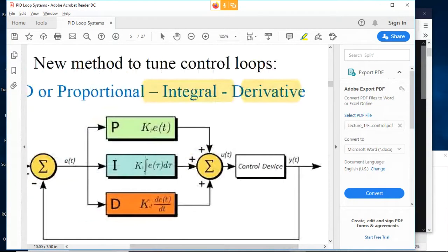So that's kind of the thing. If you increase the proportional gain, then you're just increasing your response to the error. All right. If you increase the KI term, then you're basically increasing your reaction to the summation of error over time. And so as the error gets larger and larger, then you're increasing that because you're adding that all up. This is that summation term.